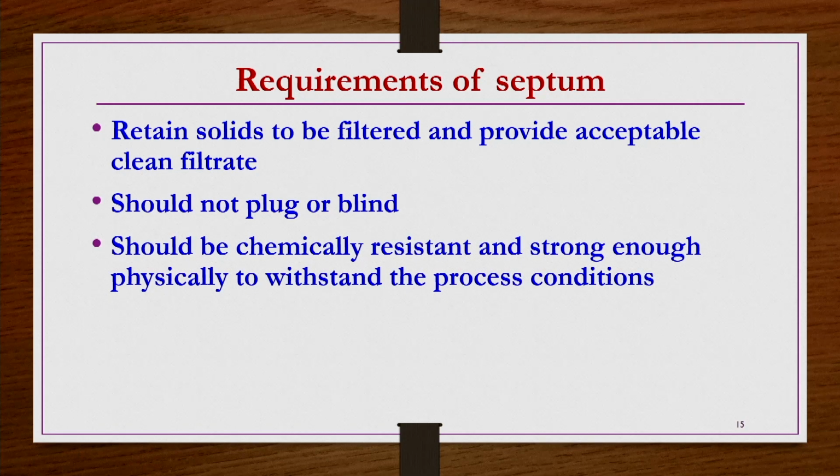These septa should be chemically resistant and physically strong enough to withstand sometimes severe process conditions applied for the required separation. Sometimes you may be applying pumps or blowers or centrifugal forces in such a way that the delta P generated may be very high, right. That is required for a given separation sometimes. Then whatever septum you take should be physically strong enough to withstand such high pressures for filtration as well.